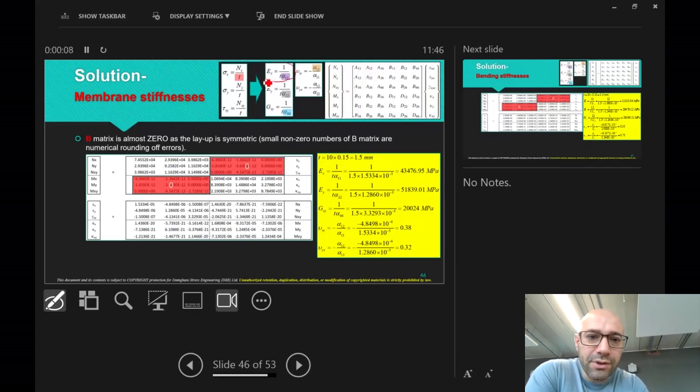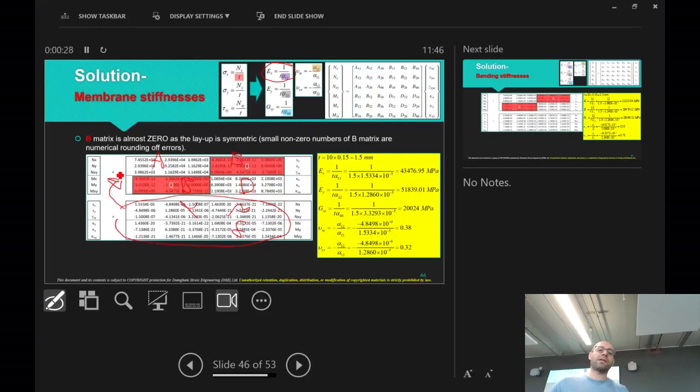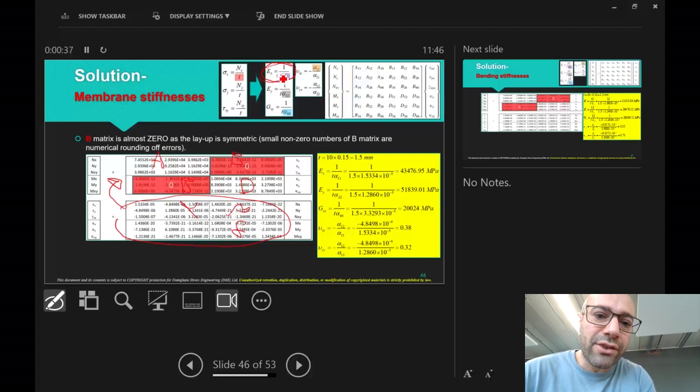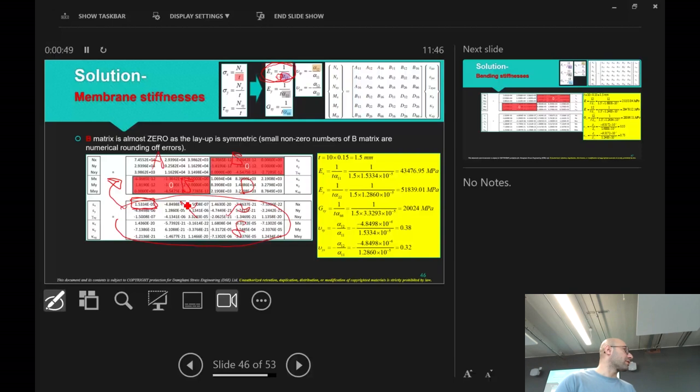So if you look at this one here, where you've got your ABD matrix, the inverse of that will give you the alpha, beta, delta matrix. So essentially this is the inverse of the above ABD matrix. Okay, you can readily obtain that via Excel, and you can see in that tool how it's done. The modulus of elasticity is defined as 1 over the thickness of the laminate, T, that's the thickness of the entire laminate, and alpha 11, which is this component of the alpha, beta, delta matrix, okay?